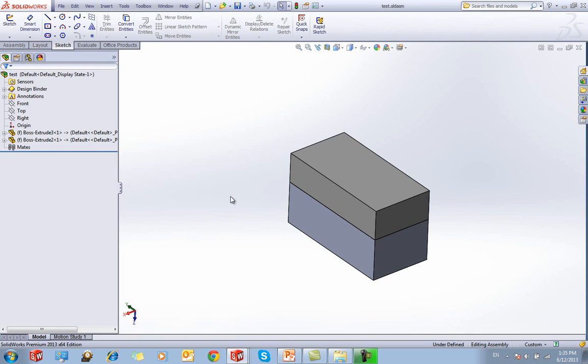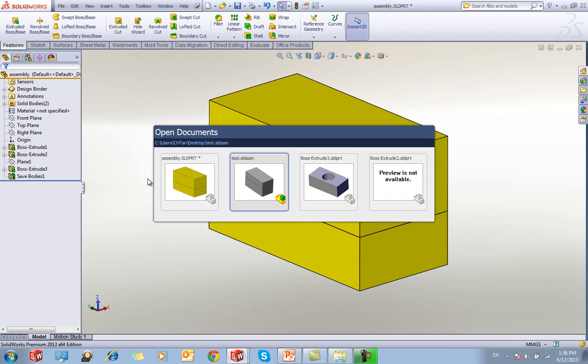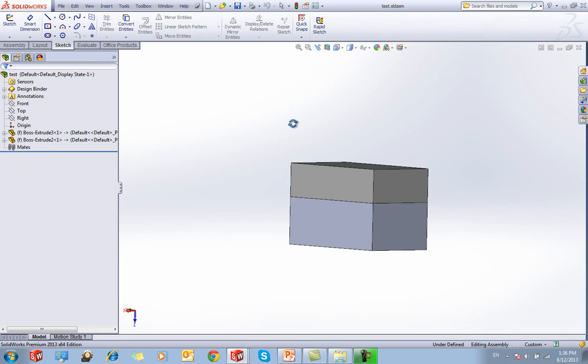This is how a mold maker normally works. When they design their part, they split their core and cavity at the part level, and then they save bodies. So these bodies can be inserted into their full mold-based assemblies, like what I did just now into these assemblies.